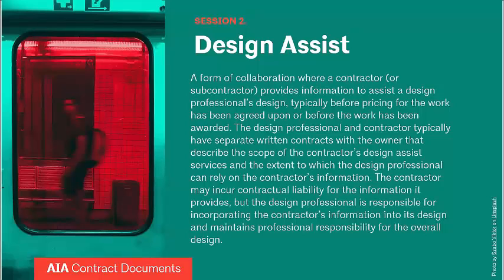So that brings me to design assist, and this is the definition that we settled on. I'm not going to read the entire thing here, but I will focus on a few key features. First, the contractor and their subs are merely assisting the design professional in a design assist scenario. They're not taking on full control of any aspect of the design or preparing formal construction documents in any way. The contractor isn't signing or sealing drawings or otherwise acting as the designer of record for any piece of the project.